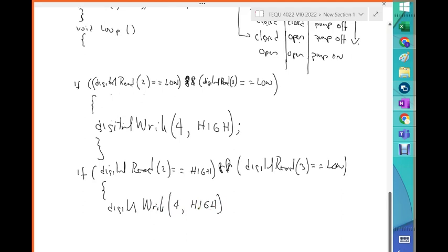For the Arduino programming that we're going to do, that high will go to an LED. Yes, right here, that's correct. Because if I don't close it, you know what that means. You have to put it in, because otherwise the Arduino code will detect that I'm missing a parenthesis right there. So basically that's what we have. Digital write 4 high, so we close here.